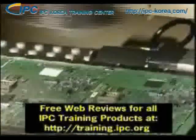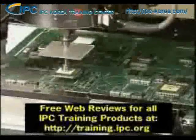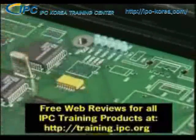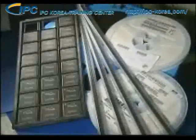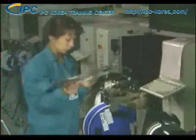What's different is that surface mount assembly is more compatible with automated processes than through-hole assembly. Because of their size and shape, many types of through-hole components require manual insertion. Almost all surface mount components can be placed by machine. The components come packaged from the manufacturer in one of 3 forms: on tape and reel, in tubes, or in waffle trays. Let's take a look at how each of these methods of packaging is loaded onto a placement machine.